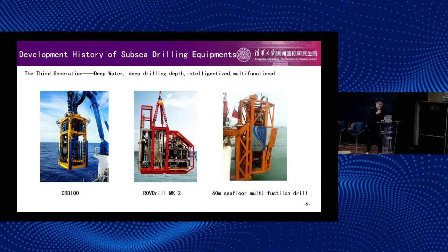The drill is designed to work in 3,000 meters water depths and continuously core to 65 meters below the seabed. The CRD100 system shown in the slide has deployed dimensions of 5.7 meters in height and 3.1 meters in width and length, making it suitable for shipping in a 20-foot ISO standard high cube container.